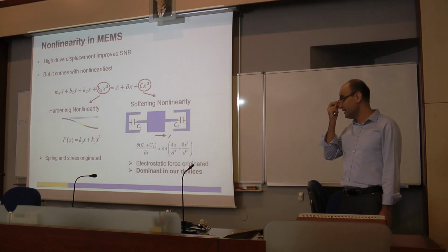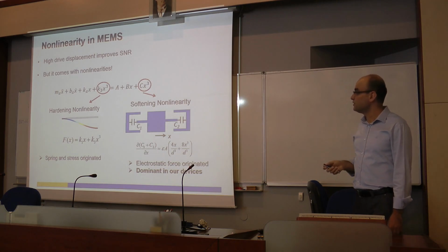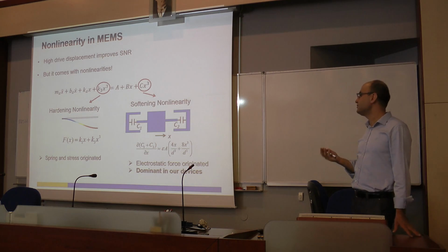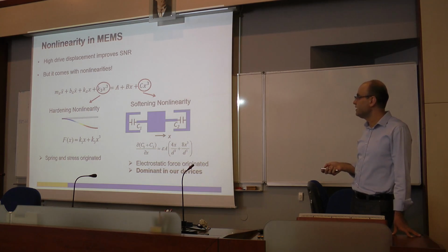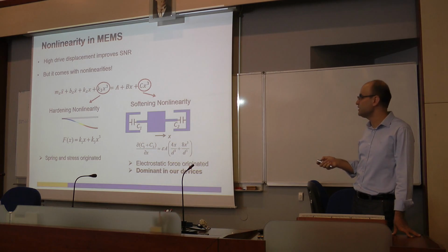Let me talk about non-linearity for a while. We like high drive displacement, or we want to displace as much as we can, because that increases our signal to noise ratio. But for MEMS, if you increase your displacement, normally this is up to this mx'' + dx' + kx, your linear equation. But if you displace too much, then k3 times x cubed is introduced.